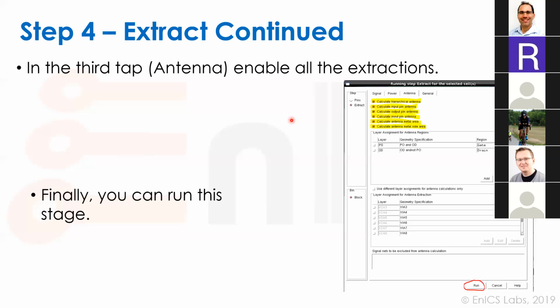Yeah, exactly. And regarding the antenna stuff, I would say even checking these things, it comes up every time. Search in your LEF file that you have the antenna information. Search for the word antenna and see that it appears, because if not, this can cause real big problems at the end of the chip implementation.